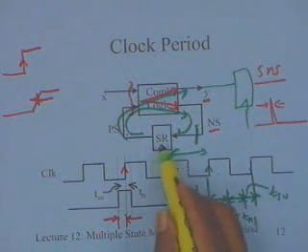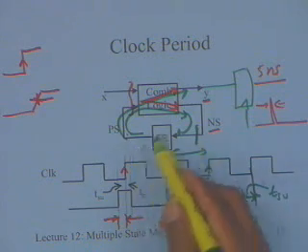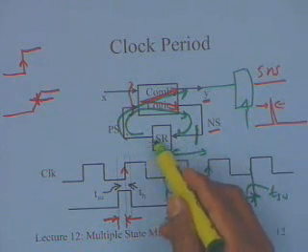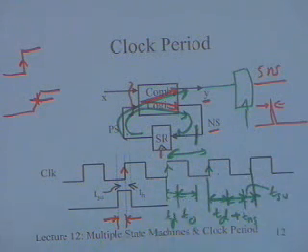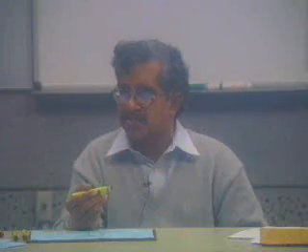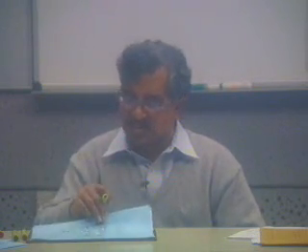But after all, if the delay is going to occur, then it is not going to change, you are not going to go out of the shift register, so the previous input will be stable. So it actually overlaps with the delay time of the flip-flop. So TH need not be added, except in a very peculiar situation where TH is very large, which is not the case. Then you have to bother about that situation, but typically that's not the case.